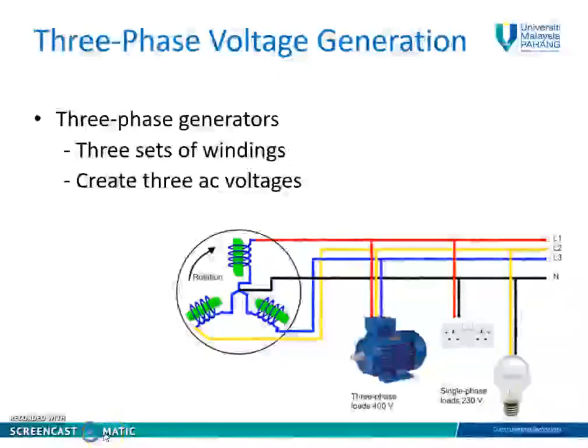The second reason why the three-phase systems are important is that the instantaneous power in a three-phase system can be constant. This results in uniform power transmission and less vibration of the three-phase machine. The third one is, for the same amount of power, the three-phase system is more economical than the single-phase. The amount of wire required for a three-phase system is less than that required for an equivalent single-phase system.